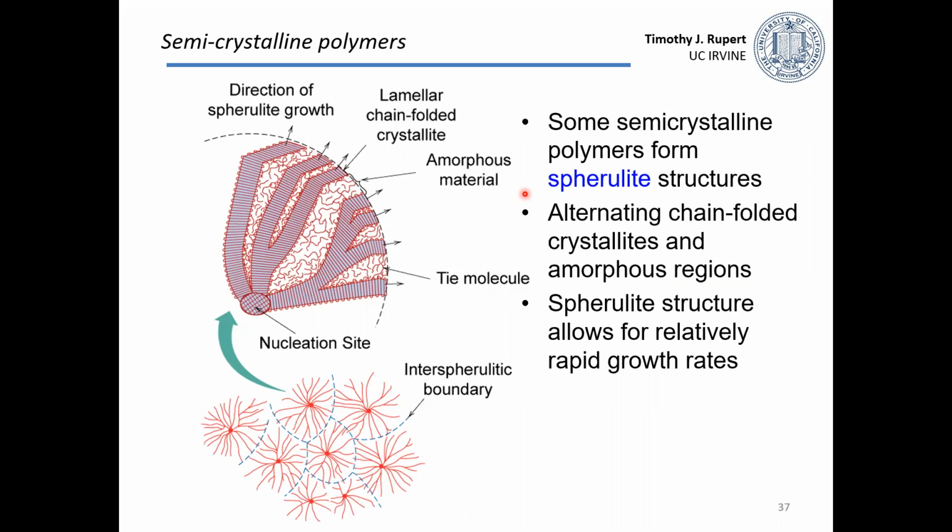So there's lots of interesting complications. One that comes about is the ways that we can mix together these ordered and these disordered regions. These semi-crystalline polymers can often have interesting structures. I'm showing one very common example here. This is called a spherulite. The basic idea is that in some region, the polymer chains become aligned.